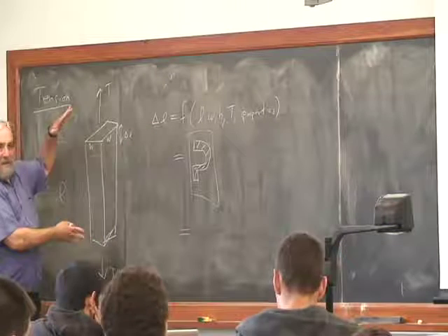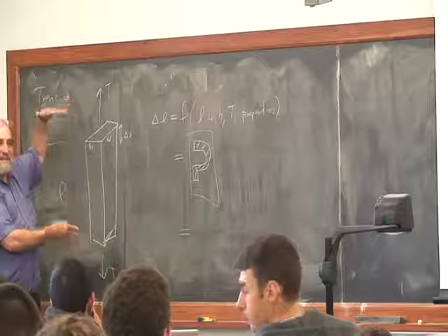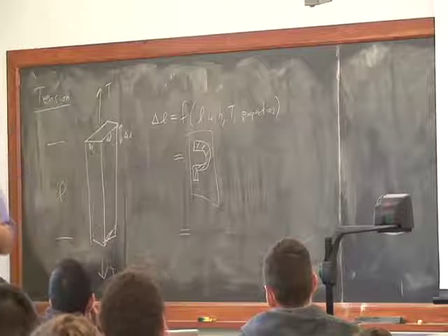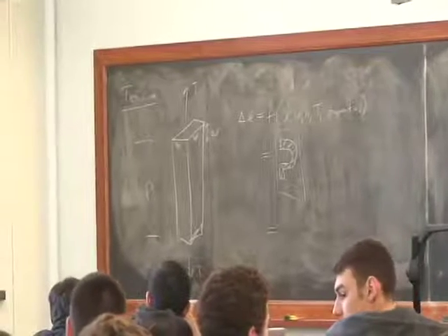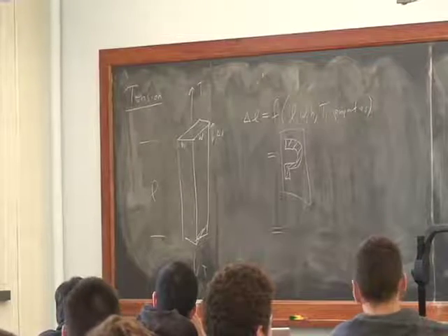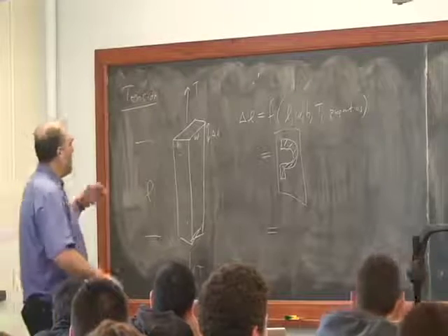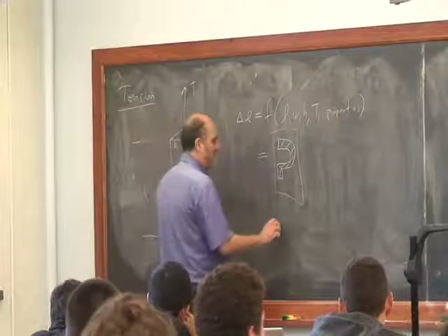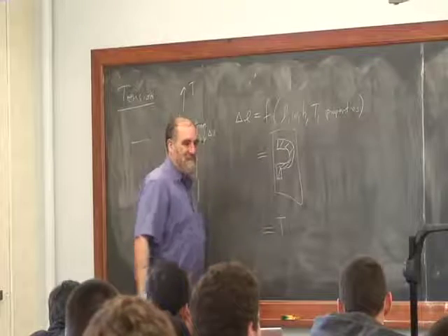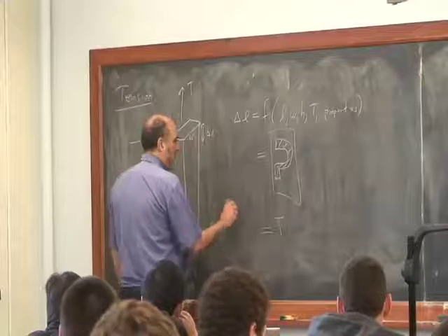We assume often in engineering and science that when you make small changes, you get small effects, and that if you double the small change, you get double the output. You assume linearity. You do something, you do twice as much, you get twice as much out. So the assumption of linearity is a good one, oftentimes for many engineering materials, and that tells us that the change in length has to be proportional to the tension. So this one comes from linearity.